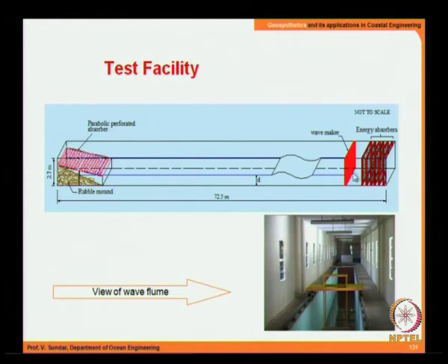It is a wet back, so you have water on the rear side of the wave maker. In order to take care of reflection within this area, we have progressive energy absorbers which absorb or dissipate the energy behind the wave maker, and we have a parabolic absorber here to absorb the incident wave energy, so that you are dealing only with progressive waves in the wave flume.